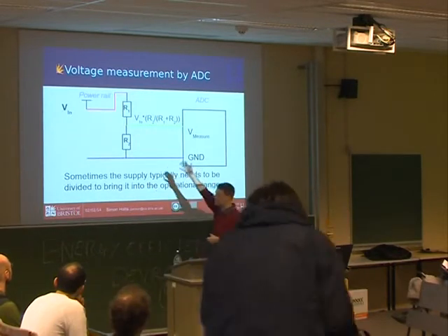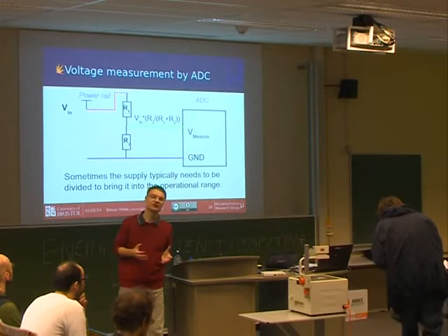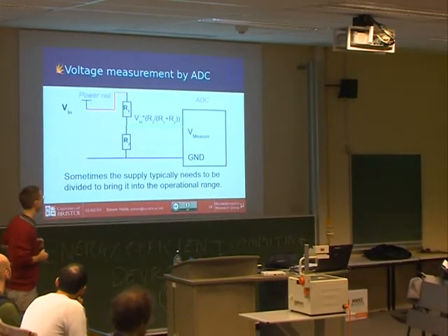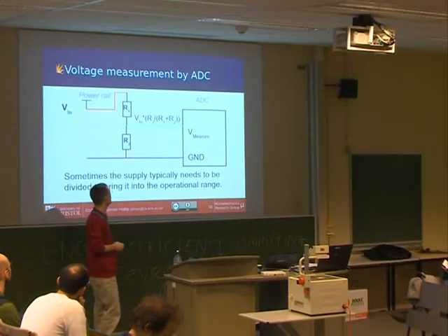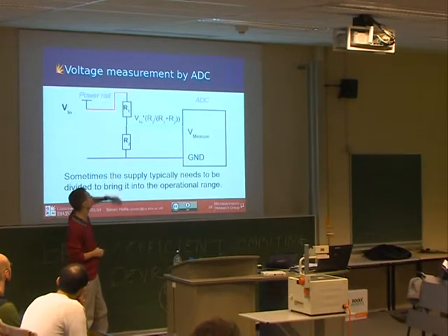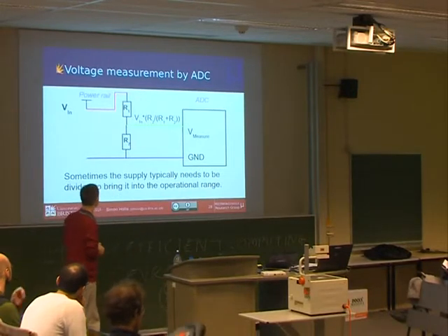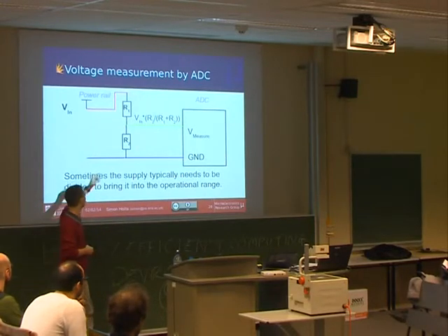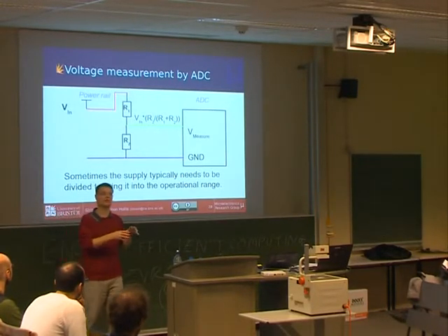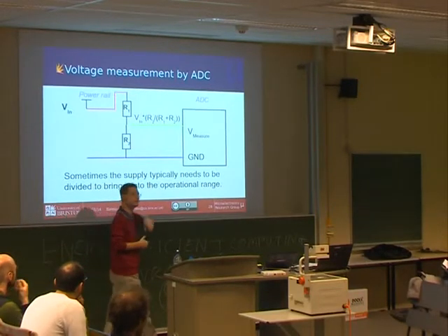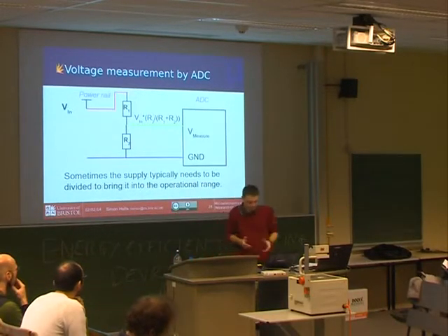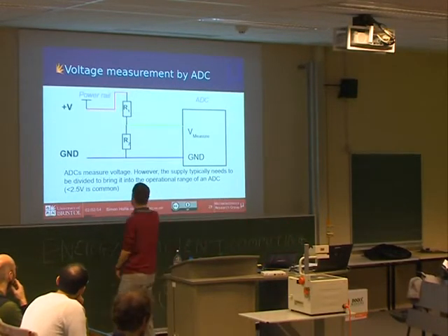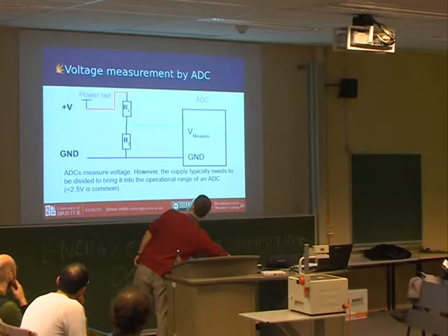The first thing we want to do, we build this structure called a potential divider. It uses 2 resistors, and that allows us to drop a high range of voltages into a smaller range. And it's determined by the equation that's up there, and V out is the voltage in times its ratio of resistors. So if we want to halve the voltage range, so we have 0 to 5 volts, we put 2 identical resistors in there, we'll get 0 to 2.5 volts out. And then we bring it into range of the ADC. So that's nice and easy, and we'll do that when we need to.